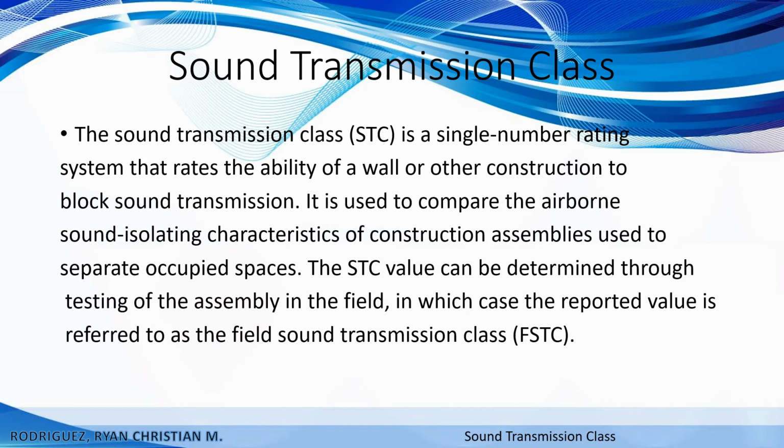So, next, sound transmission class. The sound transmission class or STC is a single number rating system that rates the ability of a wall or other construction to block sound transmission. It is used to compare the airborne sound isolating characteristic of construction assemblies used to separate occupied spaces.